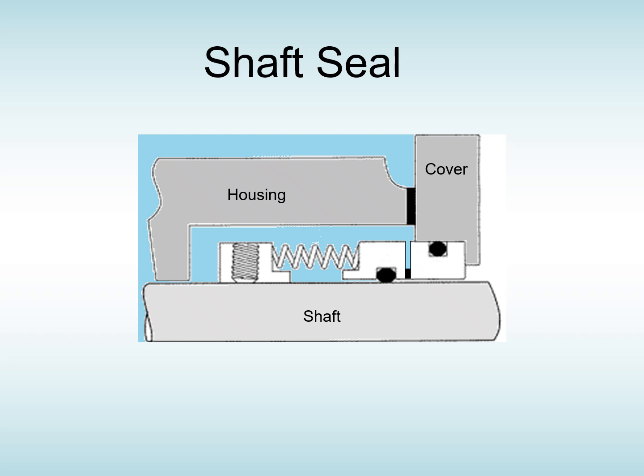Here's a cross section of a shaft seal. You can see there a gasket which prevents the gas from leaking out that way. You've got your two O-rings which stop the gas from leaking there and there. And in between you have the carbon seal which rubs against the steel part of the shaft seal, and that's what creates the seal while allowing movement.